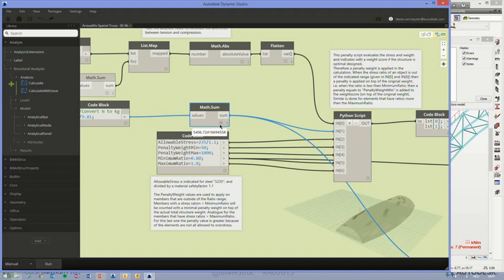And finally, let's run it. Let's bring them to the left. See, this is a whole script. I will explain to you immediately what this will do. What's happening in here is, again, taking that platform roof, performing some visualization in Dynamo for it, and here are my design parameters, which are truss height, truss width, the number of trusses, and so on. So let's run it. There you go. I don't want to have 2.58. I want something else. Okay. Let's take 2.3. Run. Yeah, works.